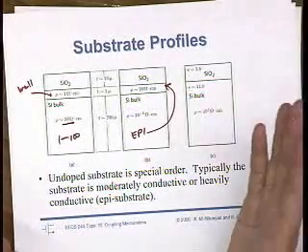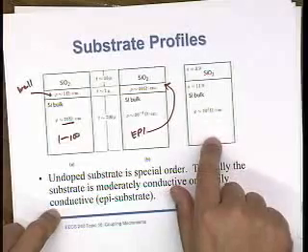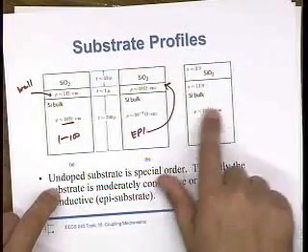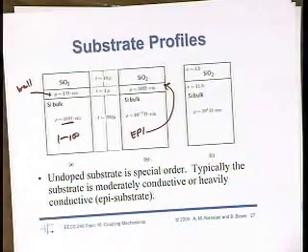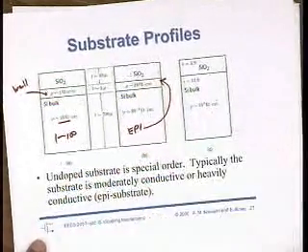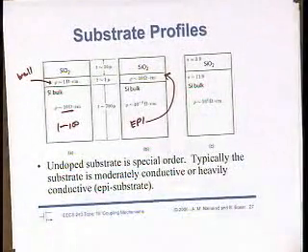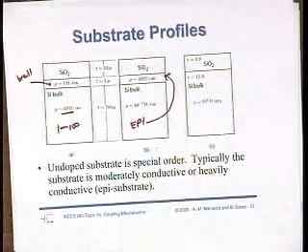Now, if we talk about other technologies other than CMOS, like SOI, then you actually can use this. There's no reason not to, because this substrate is electrically isolated from your transistors anyway, and so you don't really care. Other technologies, silicon on sapphire, again, same thing. This is just now a mechanical support for your circuits, and so the electrical properties you can design to suit your needs, and you can make this very resistive and reduce the coupling.